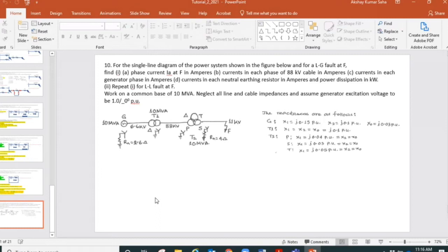If you draw two sine waves separated by a certain angle and you look at any instant of time, you will find a difference between the two voltages, because we get the instantaneous values of voltages from the sine waves. Those instantaneous differences between the two voltages will cause a circulating current between the transformers, which we don't want.